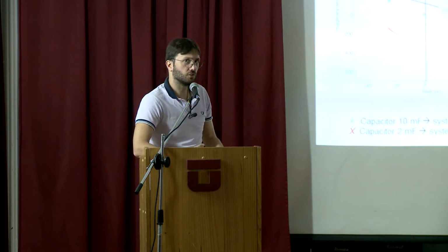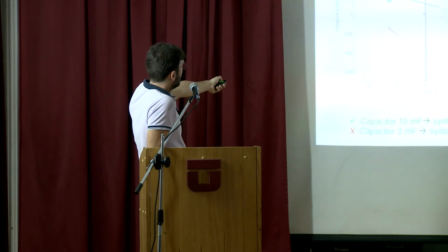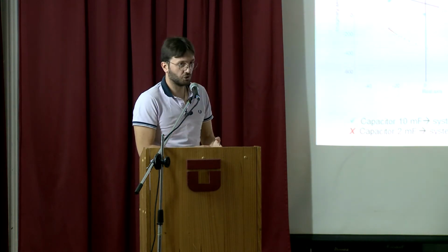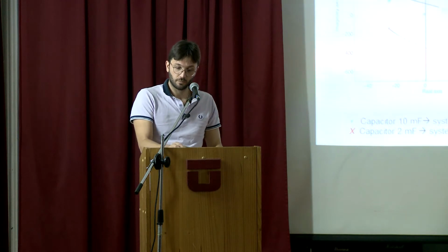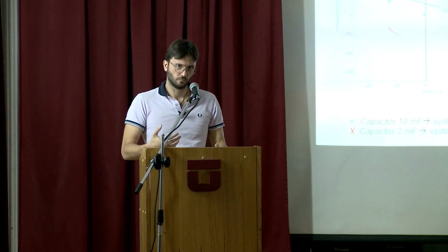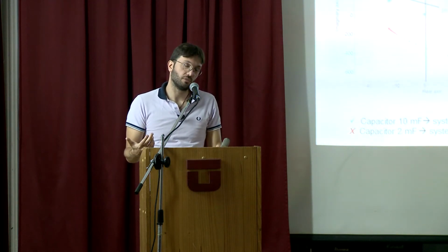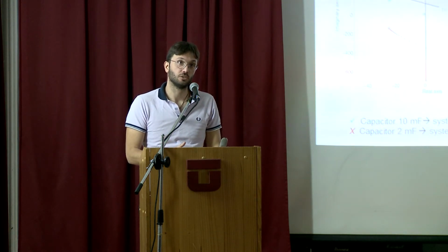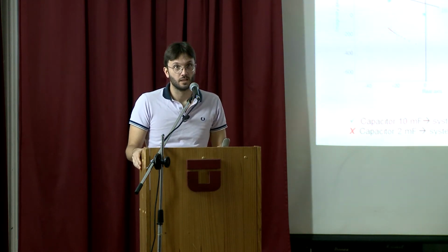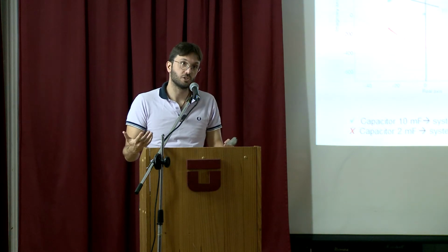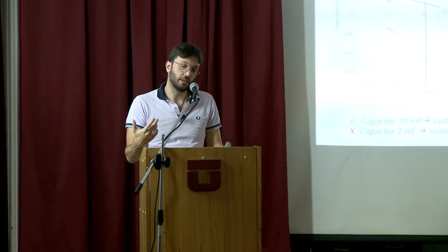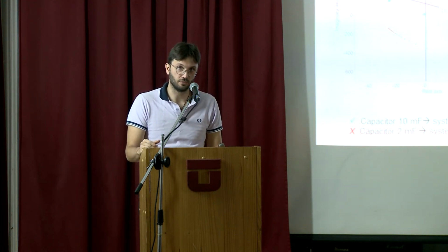If we have instead some bigger DC link capacitor, higher values, then we are having the same effect as a fast PLL. So it's basically the ratio. If you have a lot of energy storage with DC link capacitor, then your PLL doesn't need to be super fast.